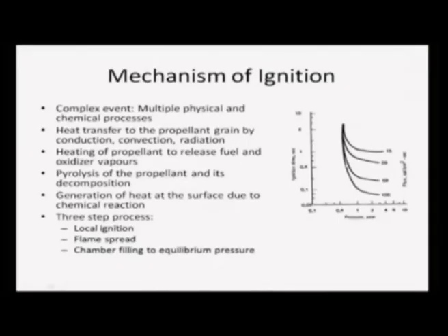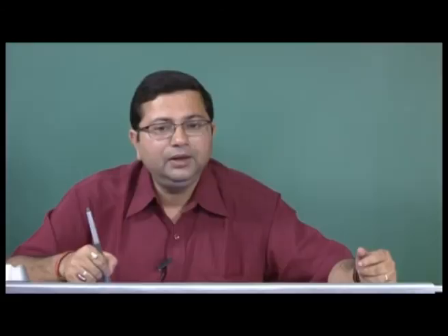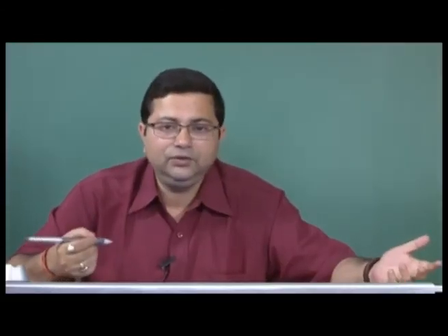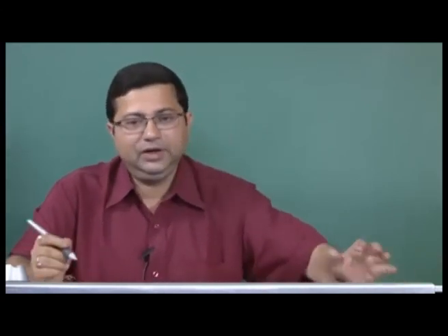Ignition time, as you can see from here, depends on the heat flux. A higher heat flux will give less ignition time, and also the chamber pressure. At higher chamber pressure, we get less ignition time. Higher pressure means the reactions will be faster, so we require less time for ignition.